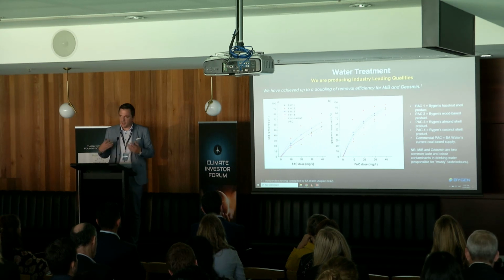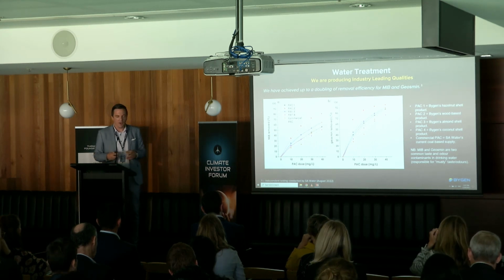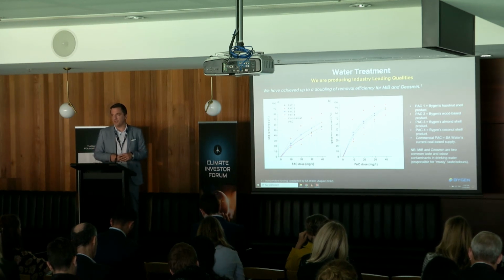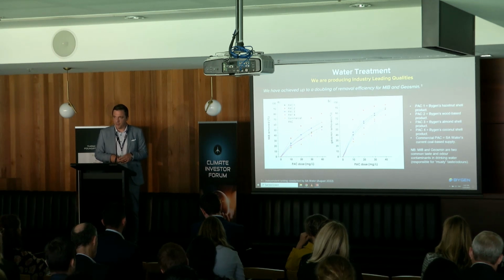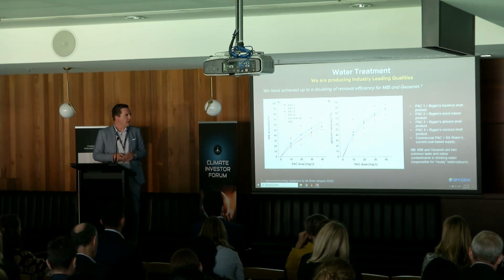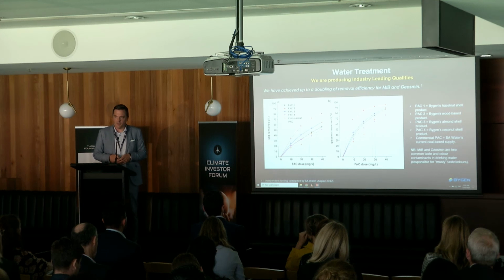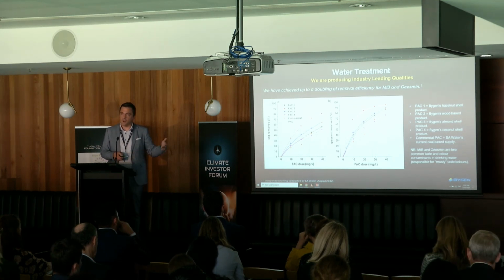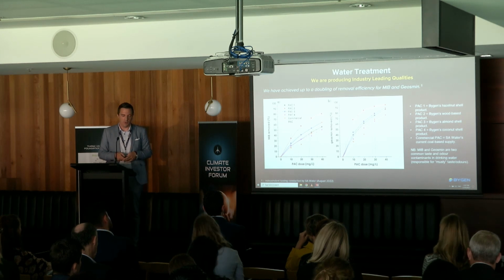And also drinking water treatment is a huge market for activated carbon. It's used in basically every water treatment plant around Australia and the rest of the world. We have done testing with SA Water, with our tailored water product, and we've shown a doubling of removal efficiency for common water contaminants compared to the current coal-based activated carbon that they use.